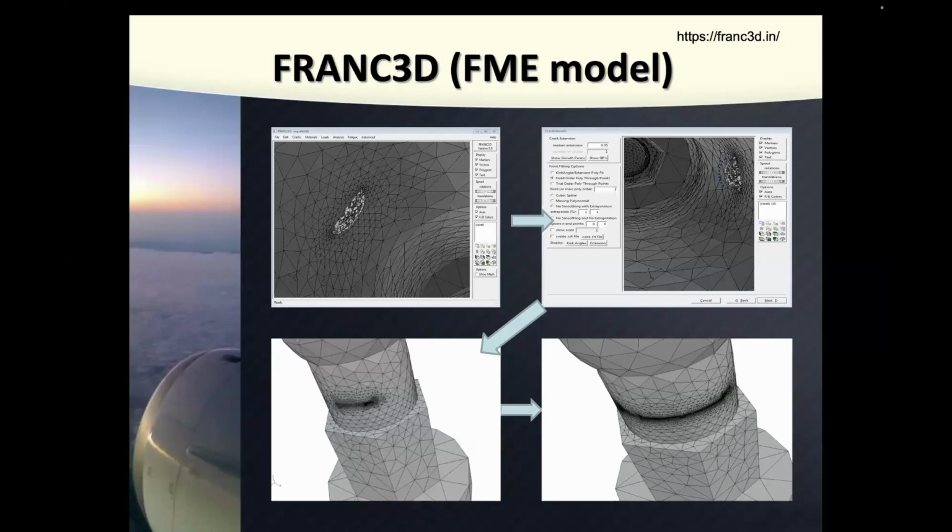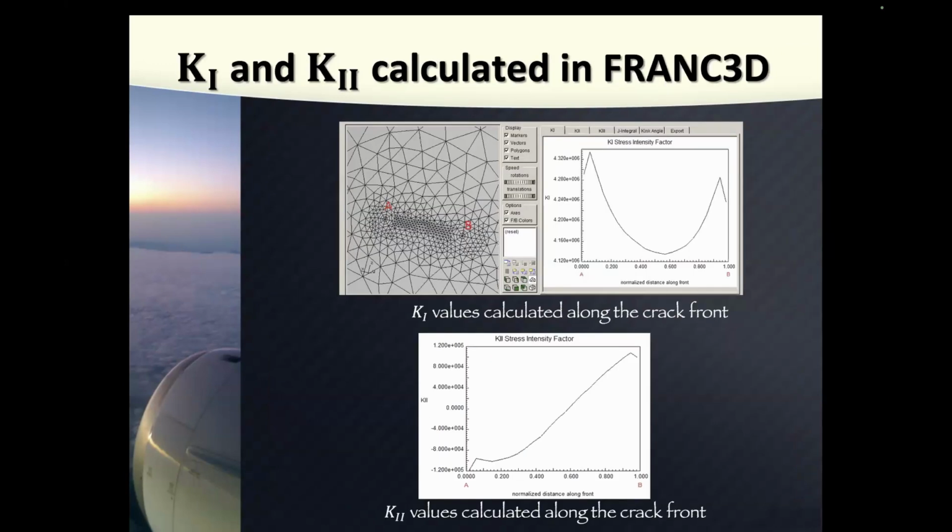And then I worked on several different projects. And for me, this was also a very good thing, because we had, let's say, a solid base for investigation, experimental and numerical. So this was a 3D implant and crack growth in a 3D implant. And you could get values of stress intensity factor along the crack front, because in the previous 2D example, we have only one crack tip. It's just one point.